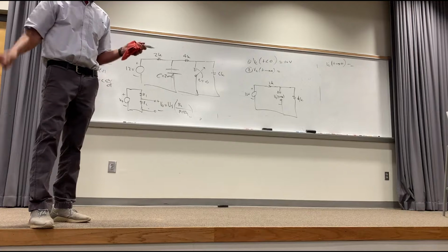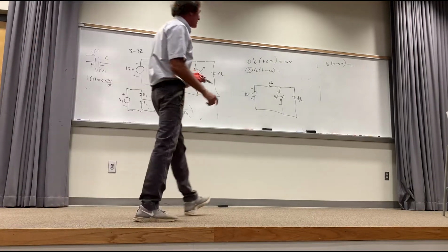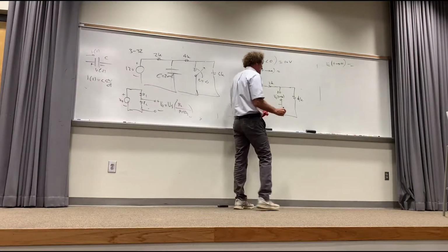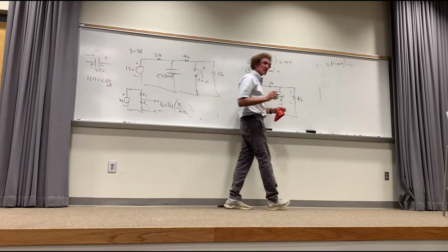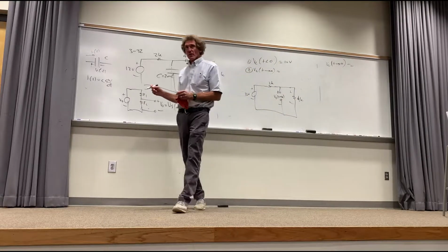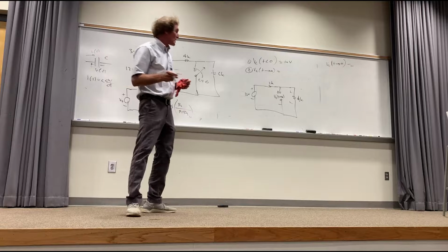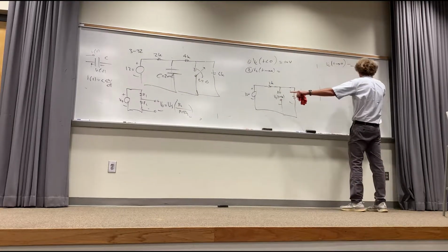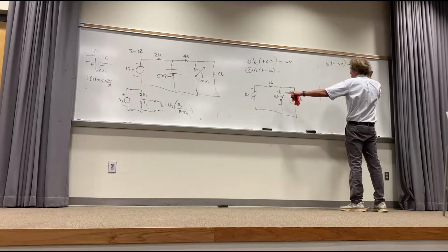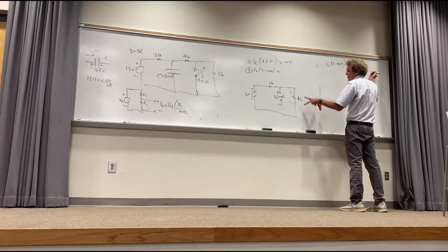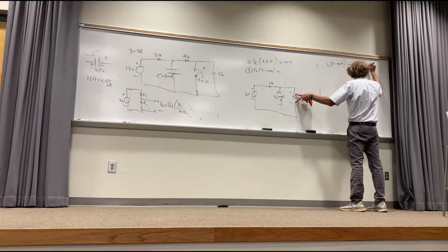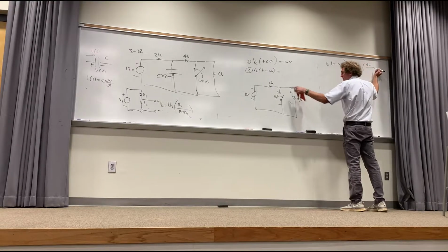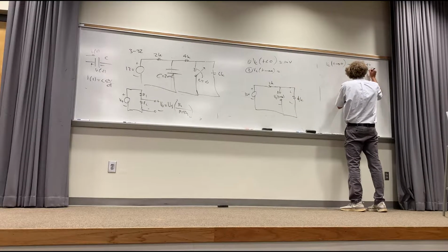That's a short circuit. Now, what is the voltage across this capacitor? It's the voltage across the 4K, isn't it, class? Everybody agree with that? So what is it? Well, source voltage would be 12, right? Then the resistance I want the voltage across is 4K over the sum of 4K plus 2K, or 6K.